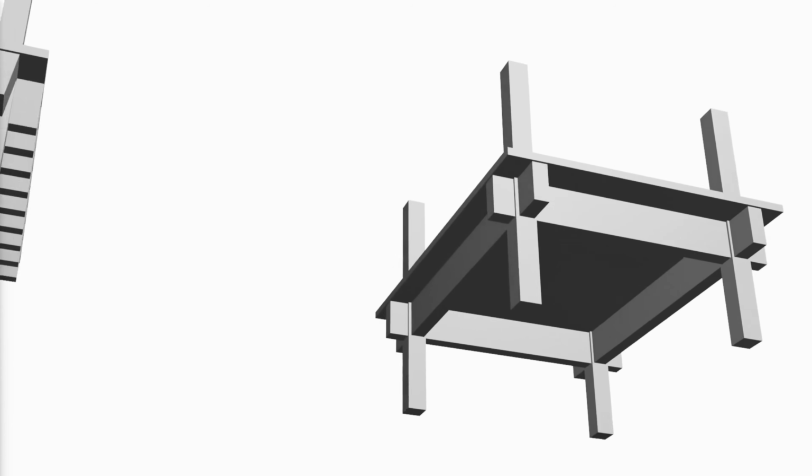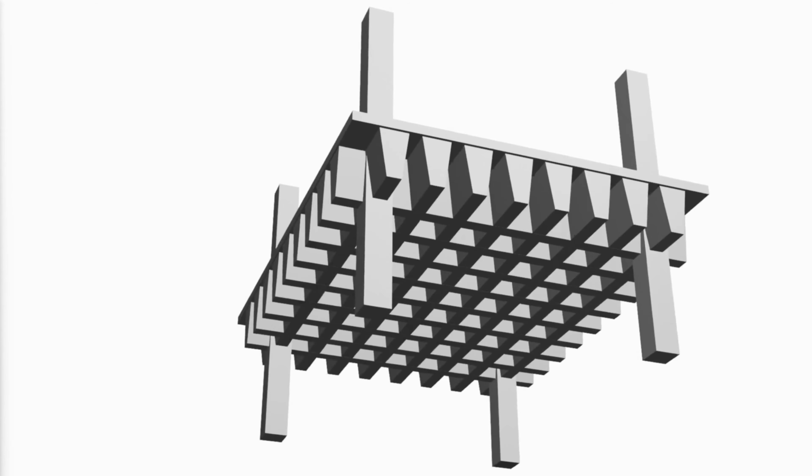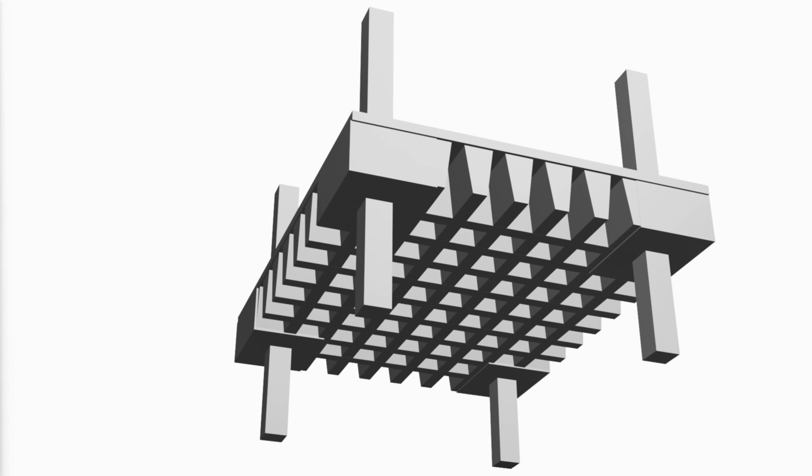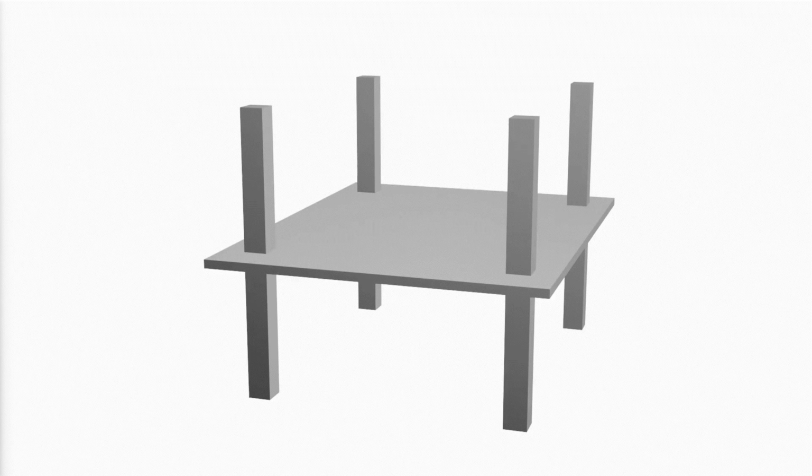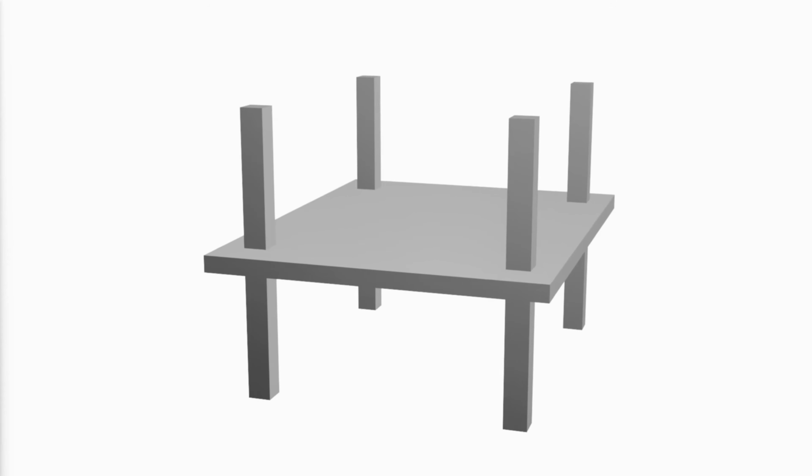Two-way joist slabs consist of evenly spaced concrete joists spanning in both directions and a reinforced concrete slab cast integrally with the joists. Solid slab sections are provided around the columns mainly to provide two-way shear resistance. Two-way slabs must have sufficient thickness so all applicable strength and serviceability requirements are satisfied.